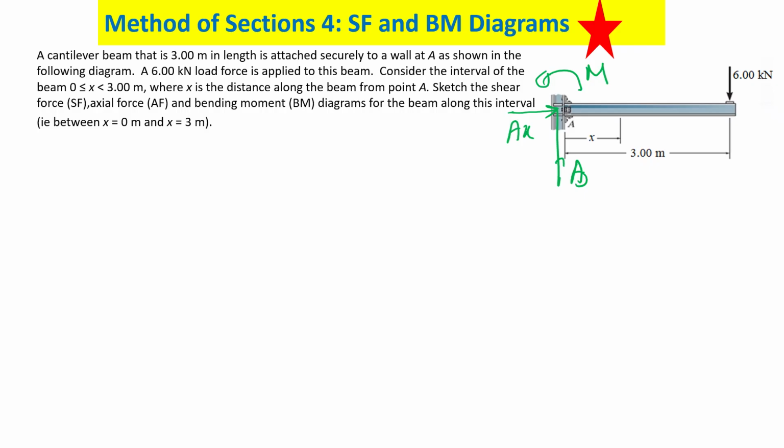In this question, the AX should be 0. Mostly in beams, we have only lateral forces. Why is AX 0? Because you don't have any force in the horizontal direction. Normally beams are like that. But in case you have a slanted load, AX won't be 0. AY should be 6, yes. Find me those 3.